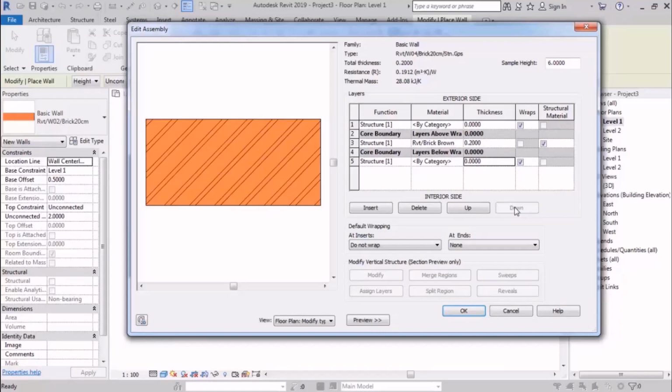There's also another important point, and that's the right place of the layers will affect the design of the floors too, because the floors, while designing, are designed based on the place of the core boundaries. So if we make a mistake here, we will have another mistake in the floors too. Alright, now that the placing is over, we want to manage the features.